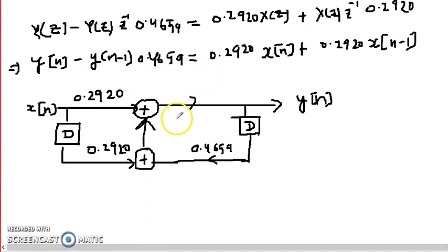As you know, this is the implementation where there is a feedback from the output side to the input side due to this connection. This connection is regarded as a feedback. And as we know, whenever the system has a feedback, its impulse response is infinite. Therefore this type of implementation is regarded as IIR implementation. IIR means infinite impulse response digital filter.